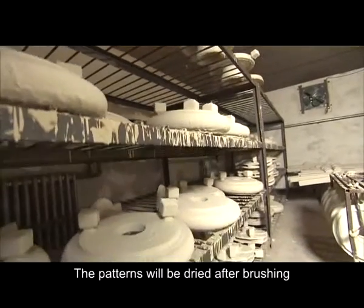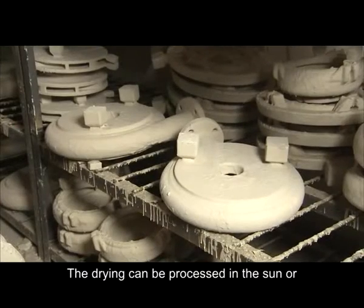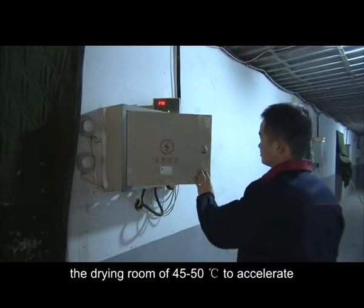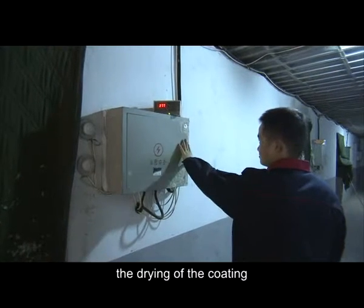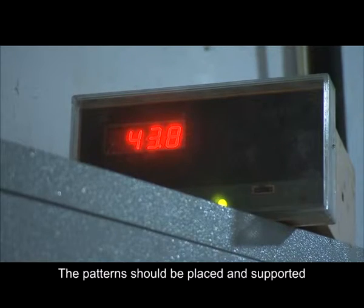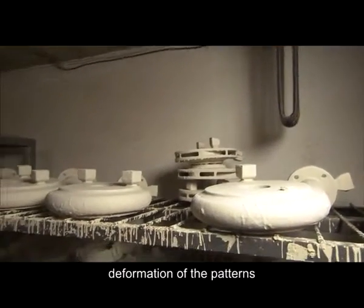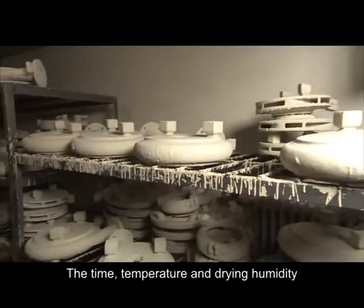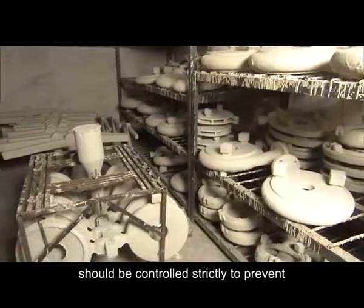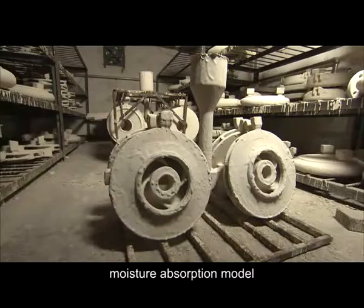The patterns will be dried after brushing. The drying can be processed in the sun or in a drying room of 45 to 50 Celsius degrees to accelerate the drying of the coating. The patterns should be placed and supported reasonably to prevent deformation. The time, temperature, and drying humidity should be controlled strictly to prevent moisture absorption by the model.